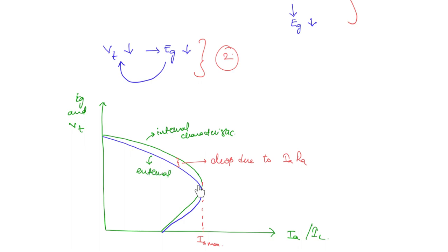So you must be wondering why this curve is taking a plunge here. What happens is, as the load increases beyond this point, the armature current will not increase anymore. Instead, the voltage will drop off even more rapidly. Now one more thing that we did not discuss here in case of shunt generator is the armature reaction. Armature reaction is a bit more complicated in case of shunt generator, that's why we are not discussing it here, okay? Now we will move on to the series generator.